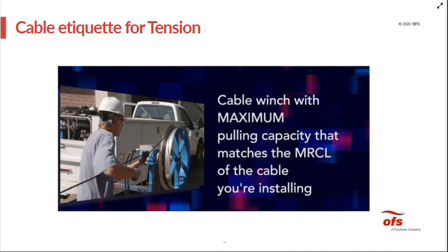In particular, what I want to talk about right now is that they both require a maximum rated cable tension of 600 pounds for the cable. Mark also mentioned that for short-term loads, we have to limit the fiber strain to 0.6%. So as a cable manufacturer, it's our responsibility to design a cable that meets both of those parameters.